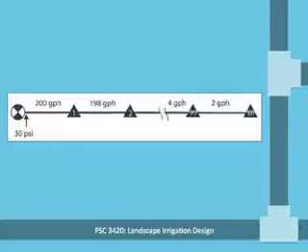Now let's look at a typical drip irrigation setup. This lateral, again, it's very similar to what you've seen just with drip emitters, but this lateral has 100 drip emitters. Only 4 are shown, and this break indicates that there are a significant number in between the 4 that are shown here. But flow here is expressed as gallons per hour, and drip tubing would be used for the lateral lines as opposed to PVC pipe. The flow in the last section of tubing before emitter number 100 would be 2 gallons per hour because each of these emitters requires 2 gallons per hour.